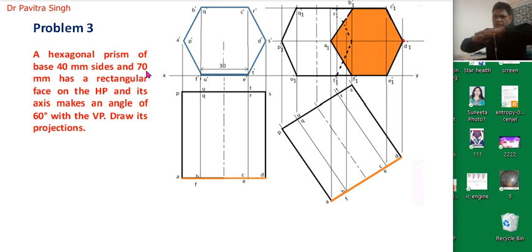this horizontal plane. Okay, means it is parallel to this horizontal plane. So now you can see, because it is lying on the horizontal plane and its axis is perpendicular to the vertical plane, you can see this from the front as a complete hexagonal surface. So this is one hexagonal lamina. So we are looking at this top surface, and the bottom surface will be behind this front surface.